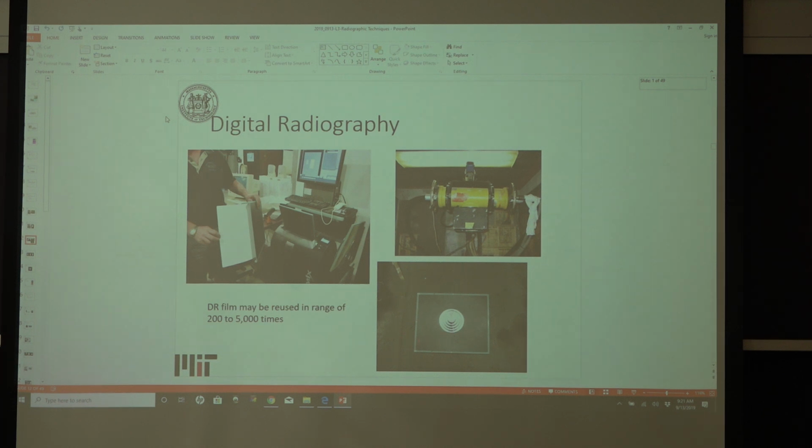This image here, we talked about it yesterday. This was the sample where the machining blade broke off during boring out the center. So what you're seeing is it wasn't able to bore through the whole center of the sample. We saw the back side of it yesterday for the UT samples where the machining blade was embedded. This would be the other side. So for this type of radiograph, you're shooting from the top down, whereas with the UT it would have been flipped on the other side. So the direction of the scan is different based on these two techniques.